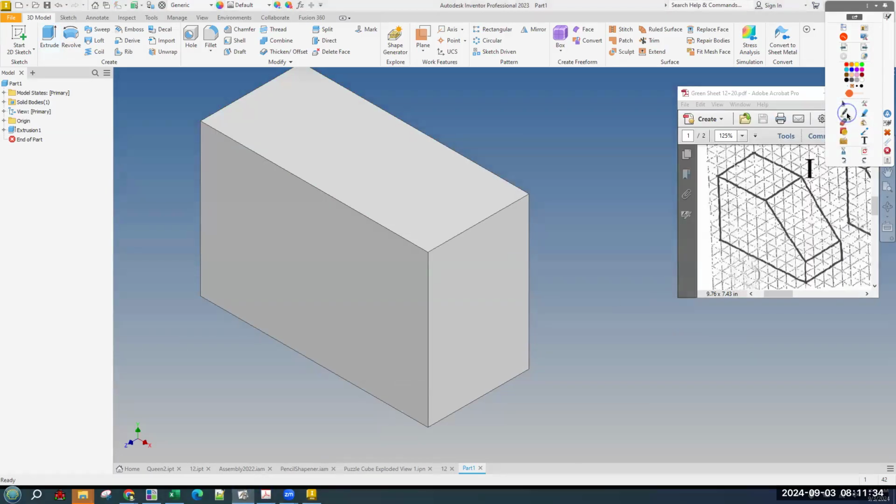and we're going to cut away everything that is not in our sculpture. And the thing we want to cut away, first we're going to draw a triangle on the front here. We're going to get a new sketch and draw a triangle that's in this exact location. And then we're going to cut extrude to remove this material we don't want. Okay, so we're going to draw a sketch on the front face.